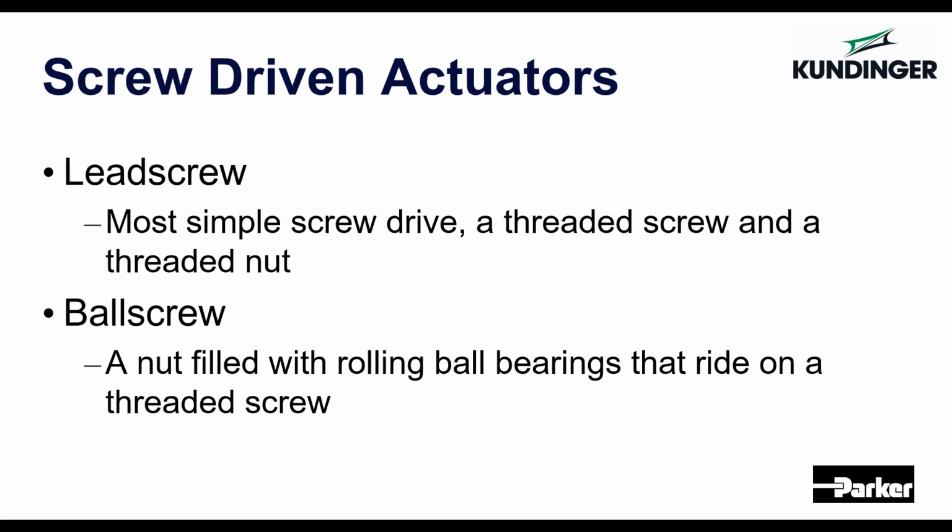Screws are pretty speed limited though. There's a concept called critical shaft speed, or commonly referred to as screw whip. It's a function of really how long the screw is, the diameter of the screw, how heavy the screw is. Eventually you can start spinning that screw so fast that it'll start looking like a jump rope. And at that case, you end up putting some pretty extreme loads on the screw and end up causing a failure pretty quickly.